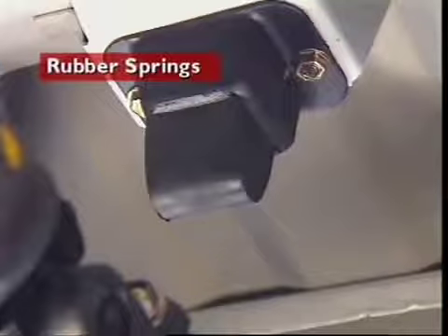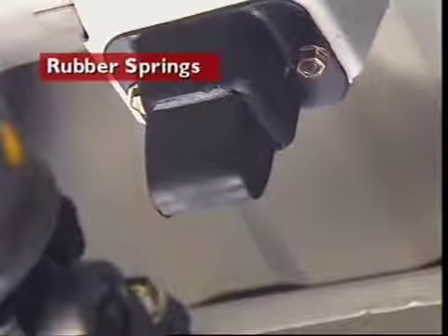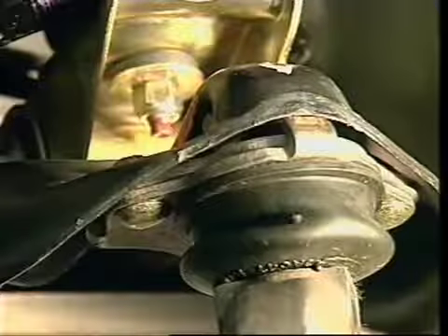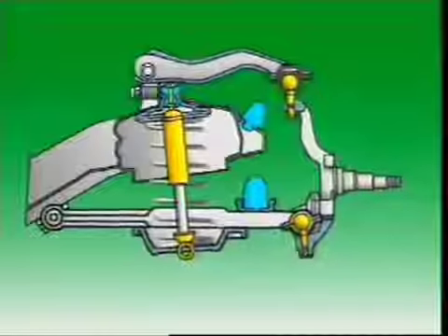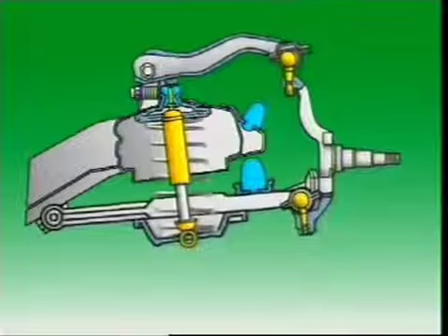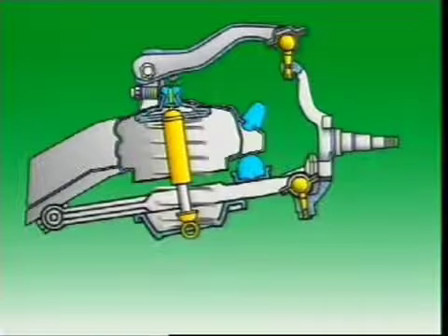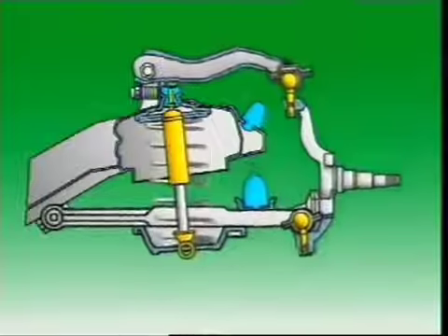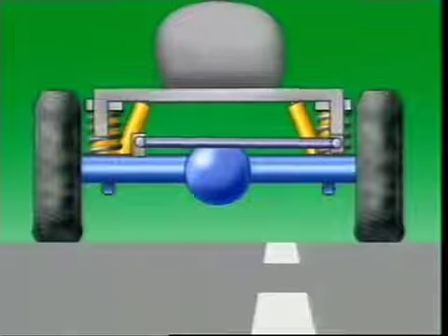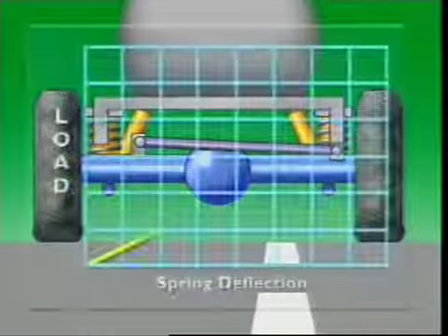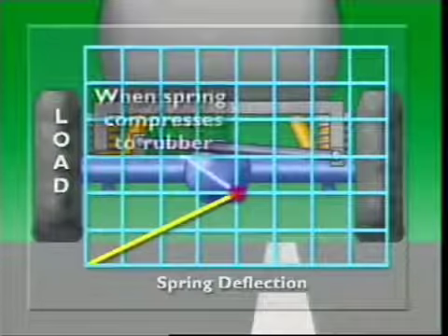This section examines rubber springs. Rubber is used in most suspension systems as bump and rebound stops. If the suspension reaches its limit of travel, these stops prevent direct metal-to-metal contact, which reduces jarring of the body of the vehicle. The stops can also be shaped to provide an auxiliary springing function, increasing their resistance progressively with suspension contact.